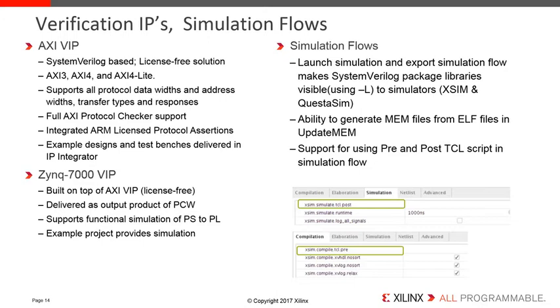Enhancements in the area of simulation flows include SystemVerilog and SystemVerilog package libraries are now recognized when launching or exporting for Vivado Simulator and Questa Sim. We also now provide the ability to generate MEM files from ELF files directly from the Update MEM tool. This is very useful for verification engineers where they don't need to run through Vivado and instead they can take a new ELF file from the software engineer and quickly see the impact of that in simulation. Also in simulation flows, there's enhanced Tcl script handling to allow using pre- and post-Tcl scripts in the simulation environment.